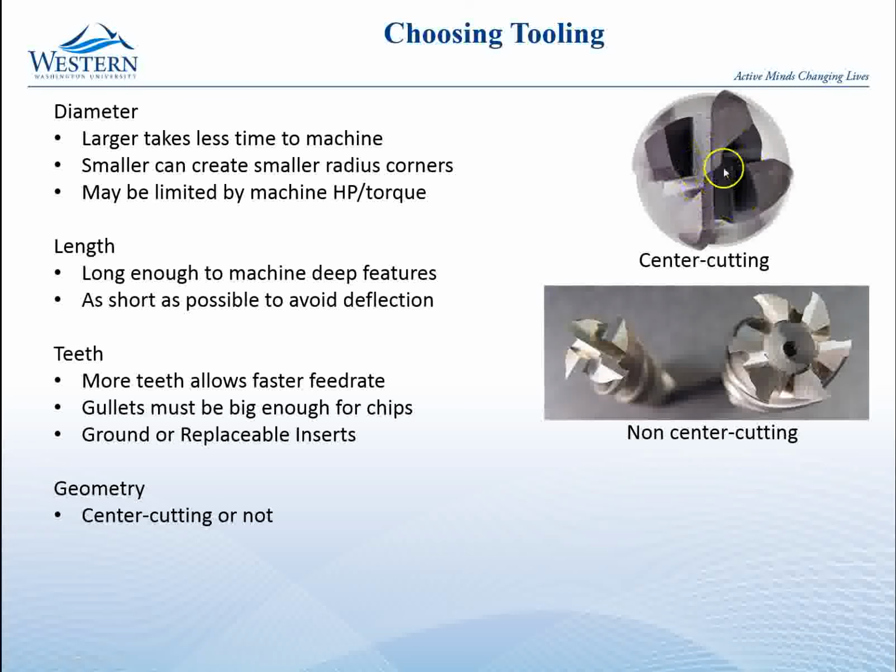So we really only use the center of the tool if we have to plunge the tool into the material. And even then, we try not to do it. We try to ramp into the material. We try to drill a hole first and then follow the hole in. You're doing that on the bases, some of you, where we're drilling a hole first and then we're plunging the tool over that hole.